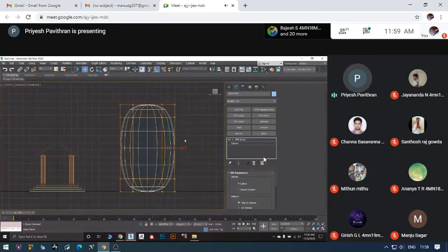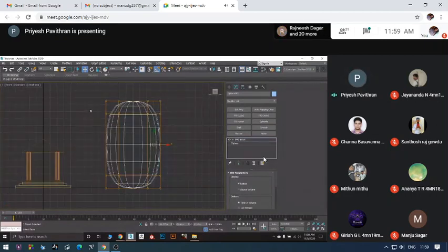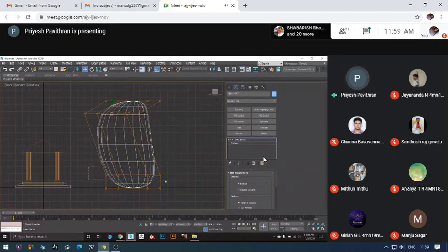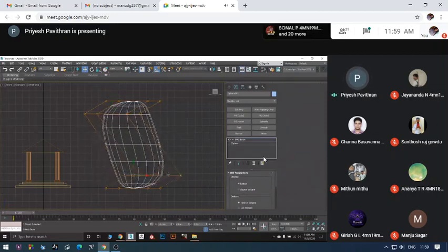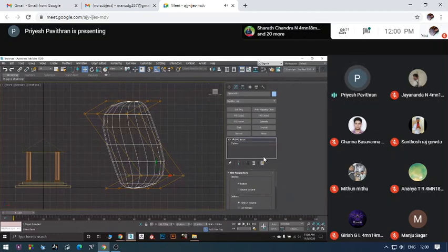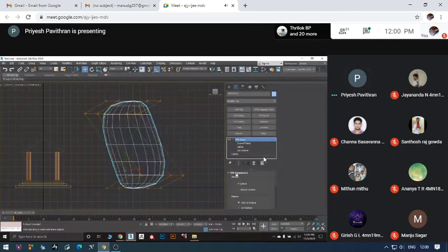If you want to make your model zigzag, just select random control points. This I make it here, and this I pulled it here. Before selecting any control point, you have to turn on the control points here. Then only, otherwise if I select this, nothing will happen. Turn on the control points, drag and select the control points.